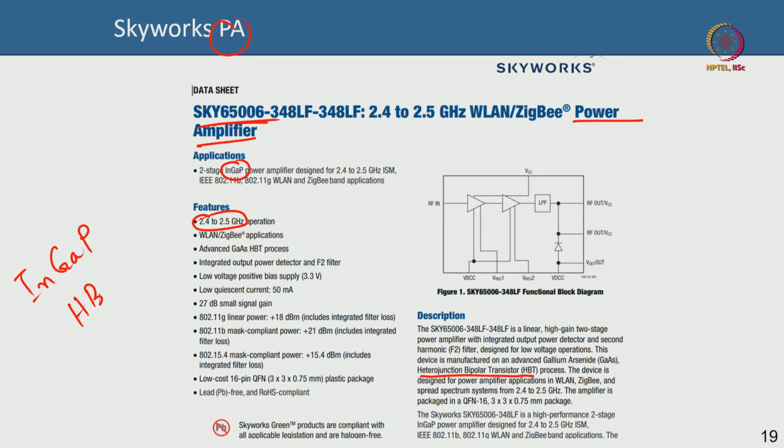HBT, just like silicon germanium, you have compound semiconductor indium gallium phosphide HBT used in a Skyworks power amplifier that goes into your iPhone 12 Pro Max most likely. So, I told you the power amplifier in your cell phone has to be a compound semiconductor HBT. For the efficiency it gives, the power handling, the knee voltage, the operating voltage, everything included, this is the best. You cannot have a silicon device there, it is an indium gallium phosphide.